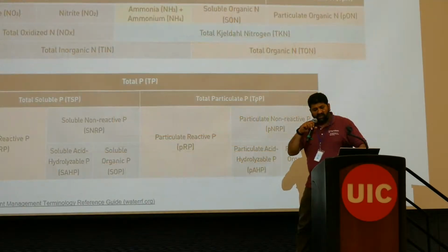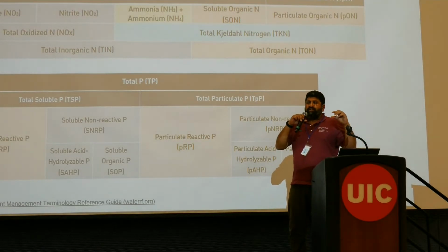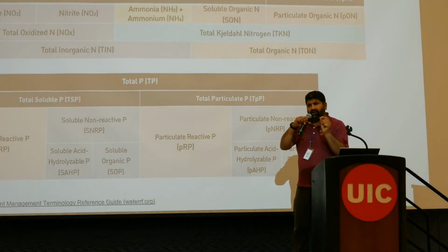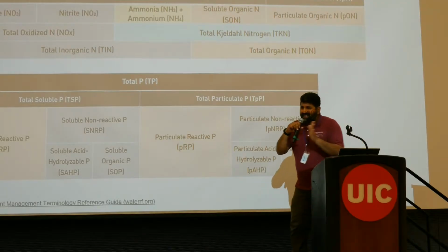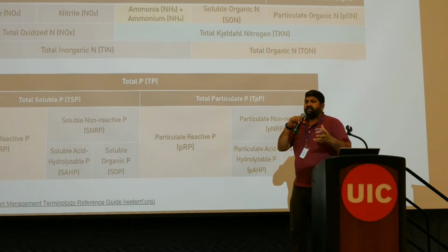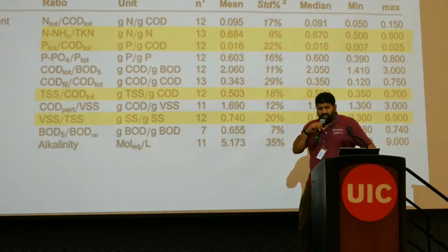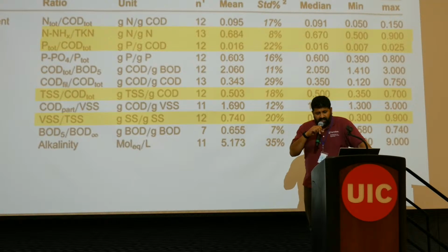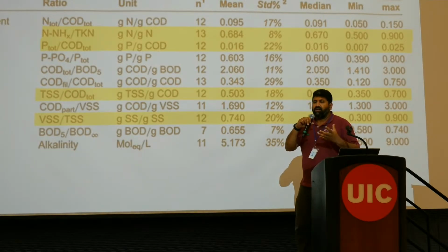And specifically when you are looking at the nitrogen and phosphorus components, when you are going to really low effluent limits, how much of that is dissolved or recalcitrant organic nitrogen? Those are the few aspects which will dictate the technology, in terms of how much the technology costs and how sophisticated it is. So just to give a flavor for this, for the ammonia to TKN ratios and the phosphorus to COD ratios, really high soluble ammonia requires a lot of energy and the technologies required.